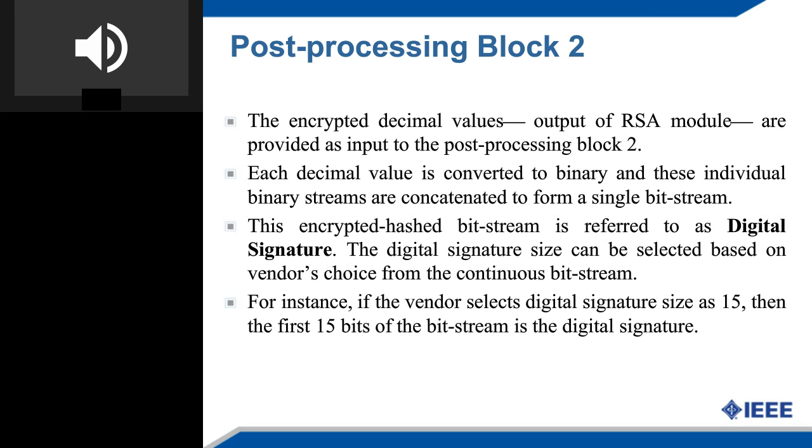Now let us talk a little bit about the embedding process of the digital signature. It can be performed using the following encoding rule. Bit 0 signifies that an artificial additional edge needs to be added between the prime node pairs of a colored interval graph. The colored interval graph is a representation of the register allocation phase of high-level synthesis. Adding an edge between two nodes means they cannot be executed by the same register, so they must have different colors and different register allocations.